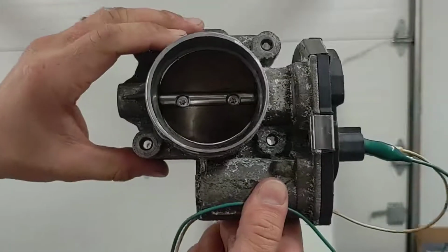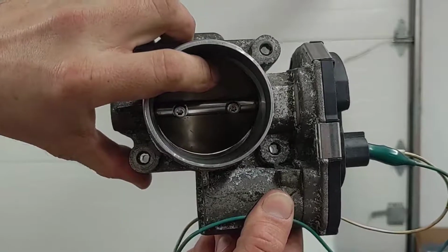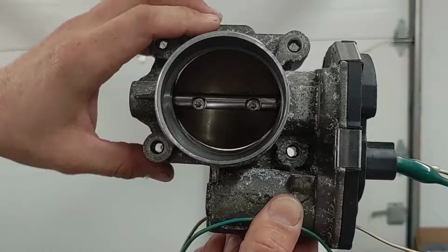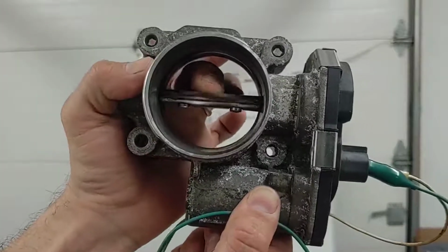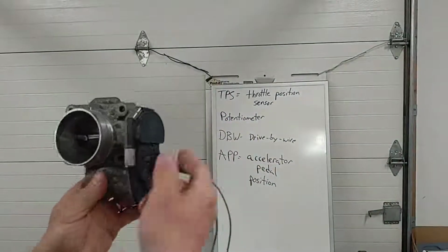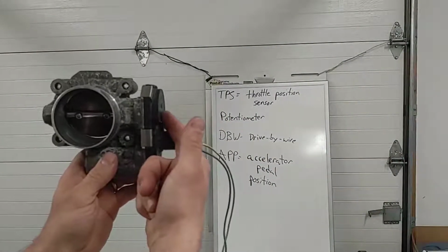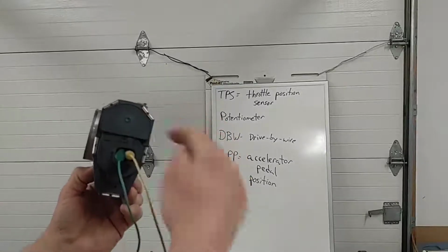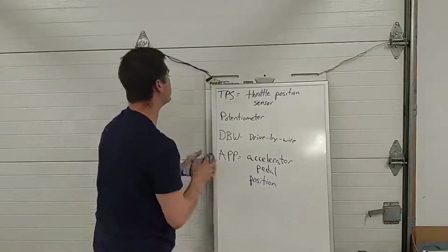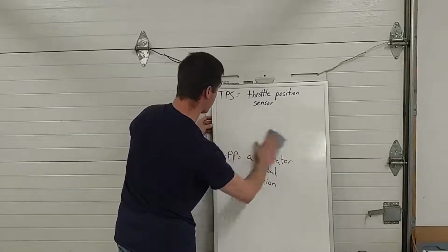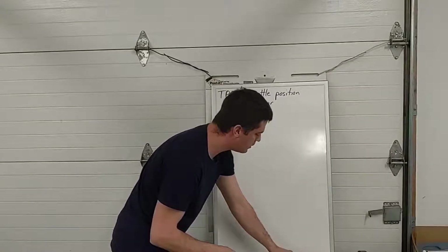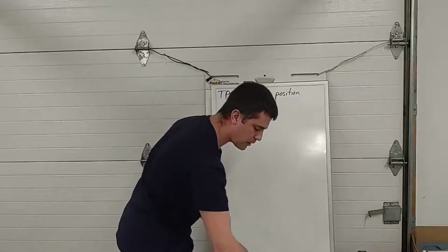When this car is idling, the computer is actually going to physically close this throttle a little bit, and then when you request the throttle to be opened, the computer is going to open the throttle a bit. It's doing that with an electric motor, which is in here, and it's monitoring the position of this with, you guessed it, a TPS. Actually, 2 TPSs are built in here. So, we'll take a moment to discuss an old-fashioned TPS and a more modern TPS. Got a little graph to show you. Then we'll talk about this throttle body and how it works.